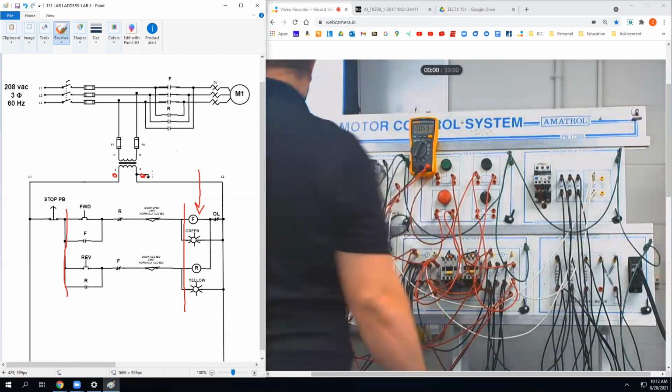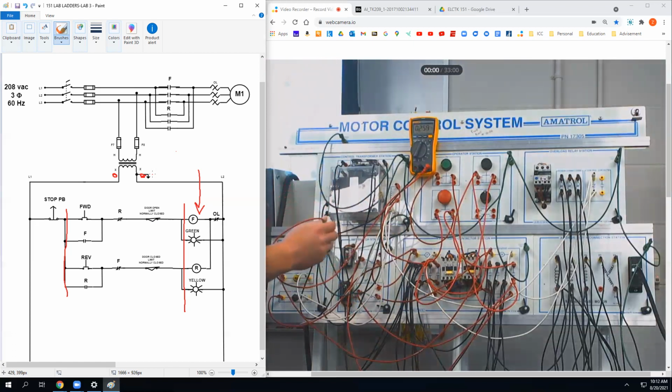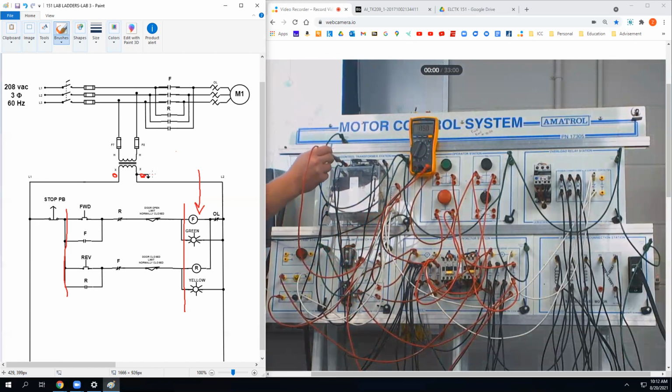What happens if I just hold the fuses and check the continuity? And you're probably going to find a problem. I just want to show you things with meters so you see. So coming in, 120 on that fuse, 120 on that fuse, 120 on that fuse, 120 on that fuse. What? Why would that be?